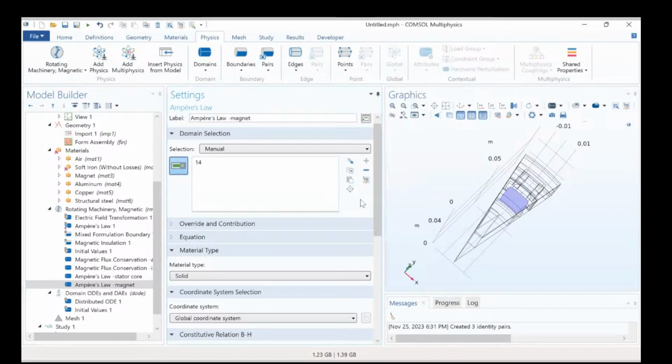We try to locate the conductor model. Okay, conductor model. And we select the homogenized multi-turn. Coil type will be numeric. And the coil currents, look at this, number of turns as well.